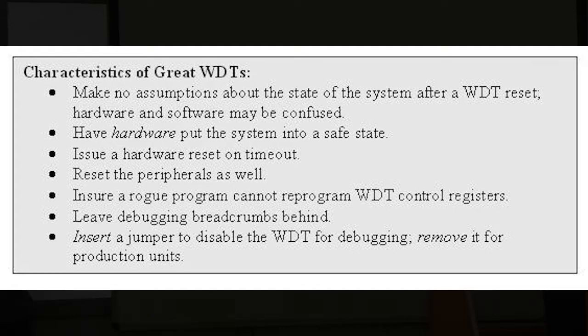You never used the watchdog timer in the labs, right? The startup codes usually disable the watchdog timer in the beginning because we don't need it for testing purposes. Only when it goes to the application level, when it is being launched, do we use the watchdog timer. So the startup code disables the watchdog timer and configures the clock of the system, whatever has to be used.